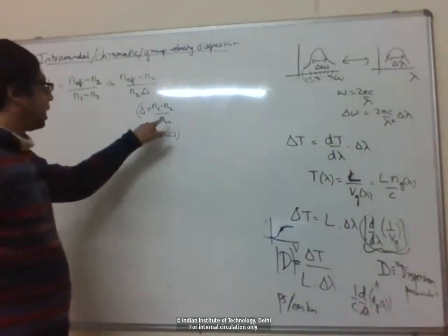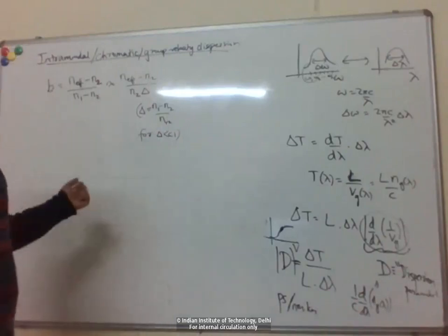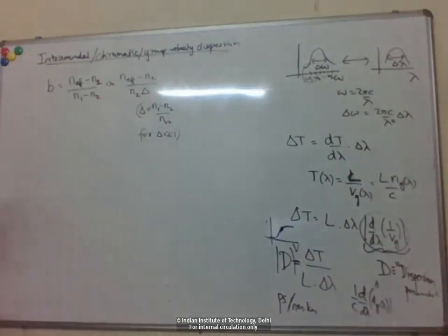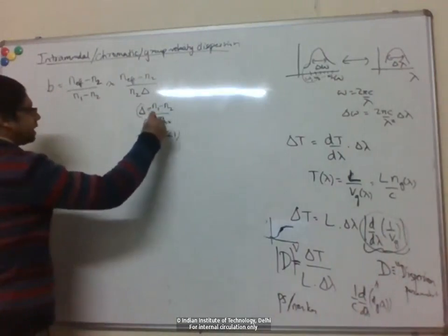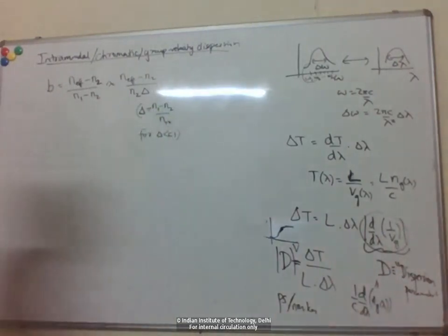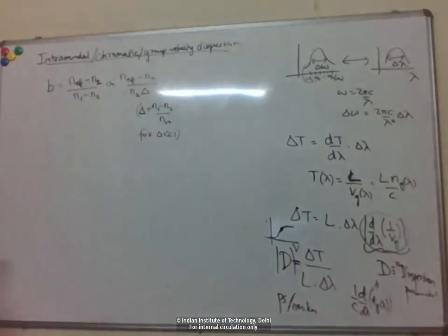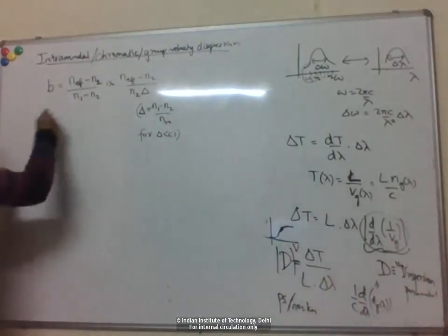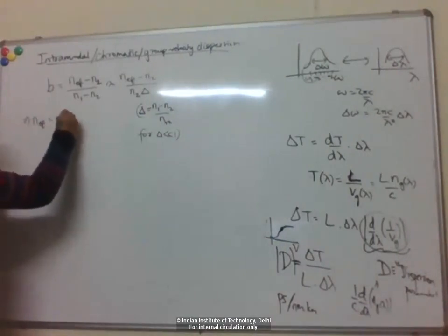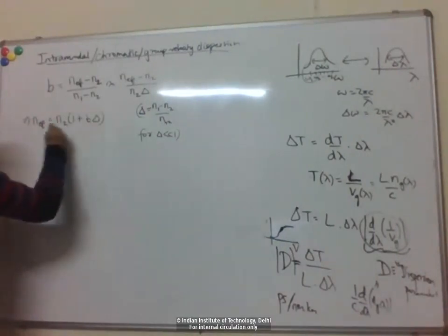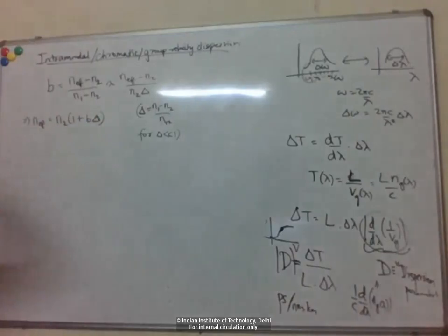For single mode fibers, for example, n1 would be 1.455 and n2 would be 1.450, something like that. So for this normalized index delta, we take the index difference and divide by either n1 or n2, and we get basically the same value. So n1 minus n2, I can write as n2 times delta. The actual effective index in terms of the normalized index, I can write like that.